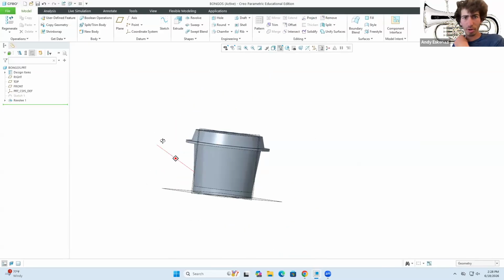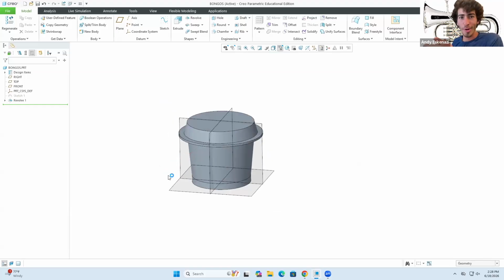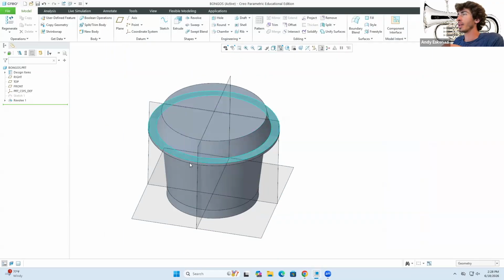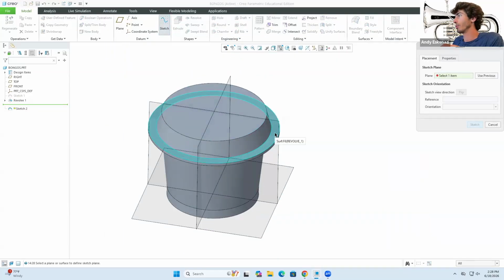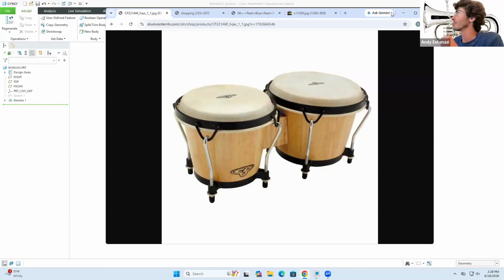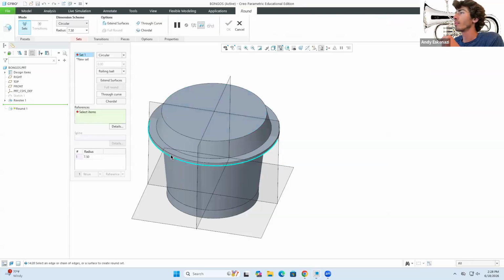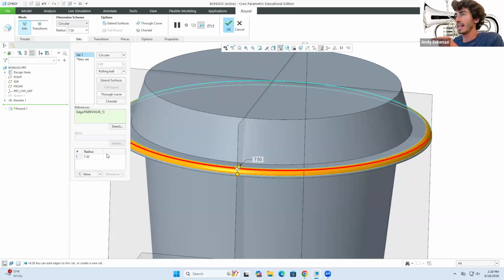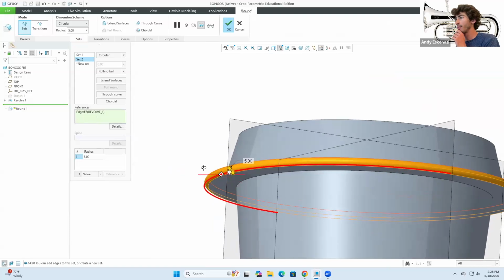Excellent. So we're making good progress with all of this. Now we can start to beautify some parts of this. So you see how here in the base plate, you have, actually let's start first by adding the black piece. So how would you do that? Well, before I sketch, I'll make that round. So I'll go here to round. We know that that is 10, which means I'll make that 5. And I'll make that 5. That way it's fully rounded like that.